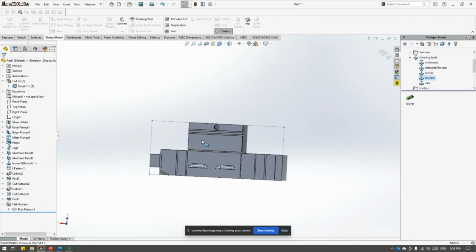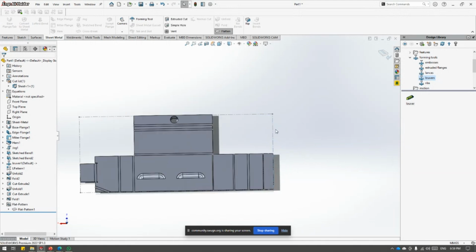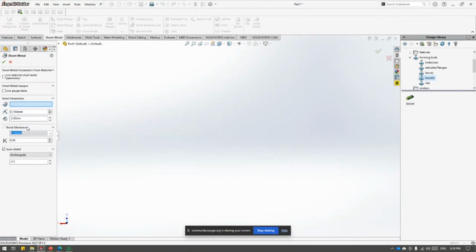And then they will ask you to go back and find something, maybe about the flat pattern. They will ask you about the length, this one, where they will put some letter and ask what the length there is. You can just click on this and measure the length from here. You can use the measure tool to measure the length as well. So this is how you change the k factor value.